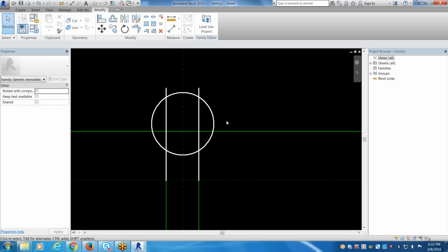All right. How about you, Ellie? Looking good? The one going up, should it stick out like yours on top? I don't know. I'm just being crazy. It looks like the circle is bigger than the. Yeah. So what I did was I moved the circle up. So select the circle, MV, and then just move it up. Keep going. See, that was not enough. It was too small. Remember I told you can't move anything under a 32nd of an inch? You had to move it more than that. Good. There you go.